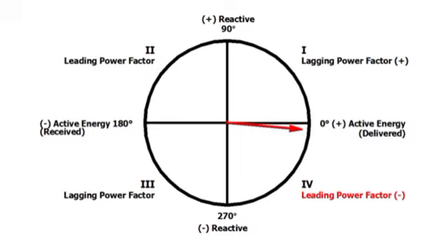When the load of the linear electrical network is capacitive in nature, then it generates a leading power factor. As against this, when the load is of inductive nature, it results in lagging power factor. In the case of leading power factor, the phase angle of current is positive with respect to voltage. However, in the case of lagging power factor, current phase angle is negative with respect to that of voltage.